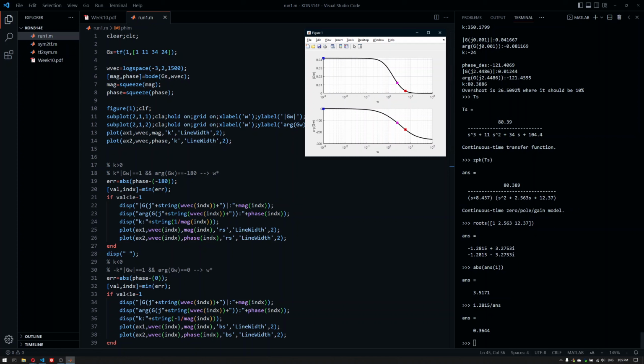But here in the Bode plot, you just have gain and phase, and you're looking for a specific phase. You use the distance, and you end up with the p-type controller. Whether it works, why it works, it doesn't really matter. You just get the result, basically. It works, but it has its pros and cons. To not know or care about the transfer function that much can be an advantage or a disadvantage.